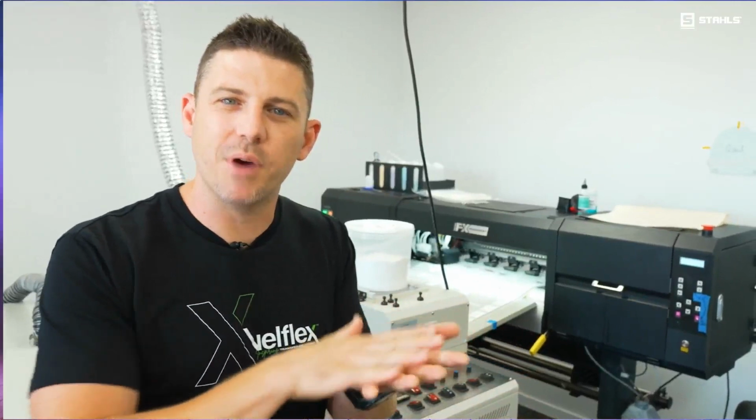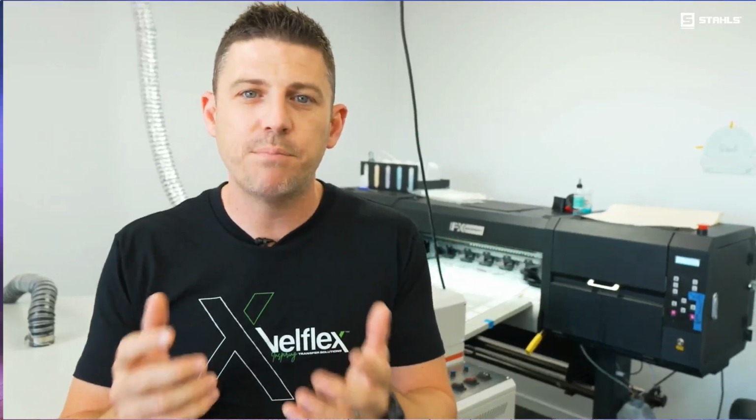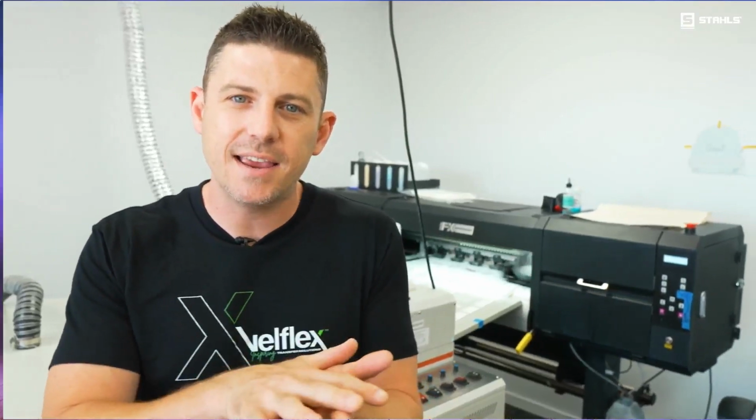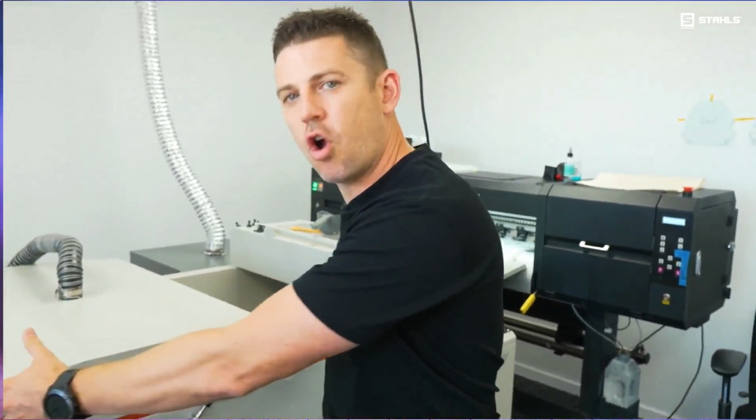What we're doing is we're using the old DTG or the current DTG technology, the similar sort of inks that are printed directly onto the fabric, printed onto the film, but in a reverse, so colored down, and then the white is printed behind. Once the white is printed, it goes through a powdering process where the glue is applied. So we are putting glue onto the back of this ink, and then it's cured in a curing process through like this dryer right here.